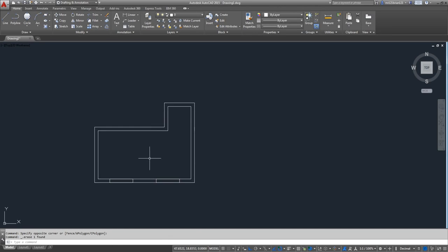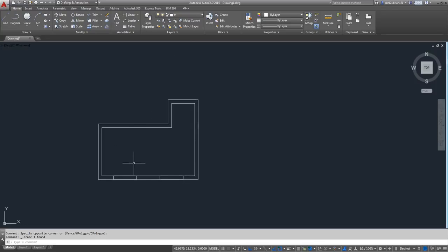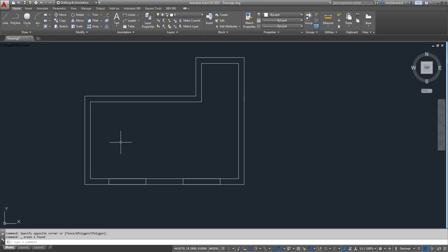Something very important to know is that when we are drawing in AutoCAD, we have to make layers. The layers are going to be very important, because when we are making a floor plan or whatever drawing we want, sometimes we want to turn off some things, like for example the equipment, and see the lightings, and see other things. For example, it's not the same plan for the blueprint. It's not the same for an extrusion as for the plumber. And that's all you have to know.